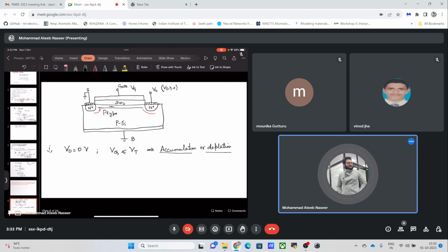this channel will not be formed. We will be having no channel in that case, and as a result the connection between these two N plus regions will be missing, so no channel will be formed.